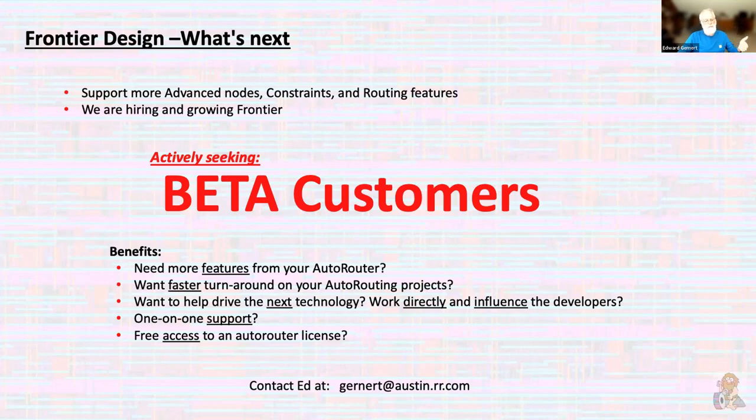So let's say you have a Cadence or a Synopsys tool or a Siemens tool. You can use our router versus their router. Again, we support OpenAccess. So you would do your placement, you do everything else, and when you want to do the routing, you would come to our tool, route it, send it back through OA, and then back into their tool. We are just focusing on routing, and that's where all our expertise comes in.